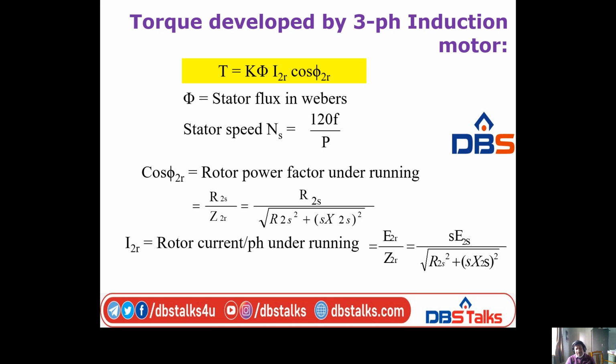Now the torque equation of a three-phase induction motor. Let us consider a three-phase AC supply given to the stator. It develops a rotating magnetic field. That rotating magnetic field interacts with the rotor, and then it develops torque. Because of the torque, the motor rotates with some speed.